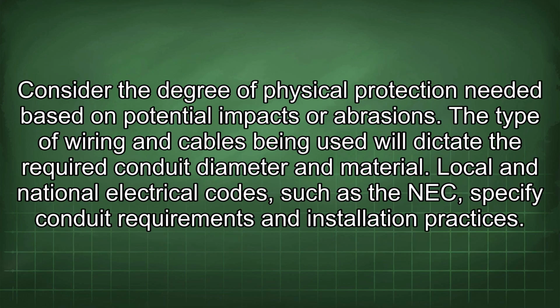Consider the degree of physical protection needed based on potential impacts or abrasions. The type of wiring and cables being used will dictate the required conduit diameter and material. Local and national electrical codes, such as the NEC, specify conduit requirements and installation practices.